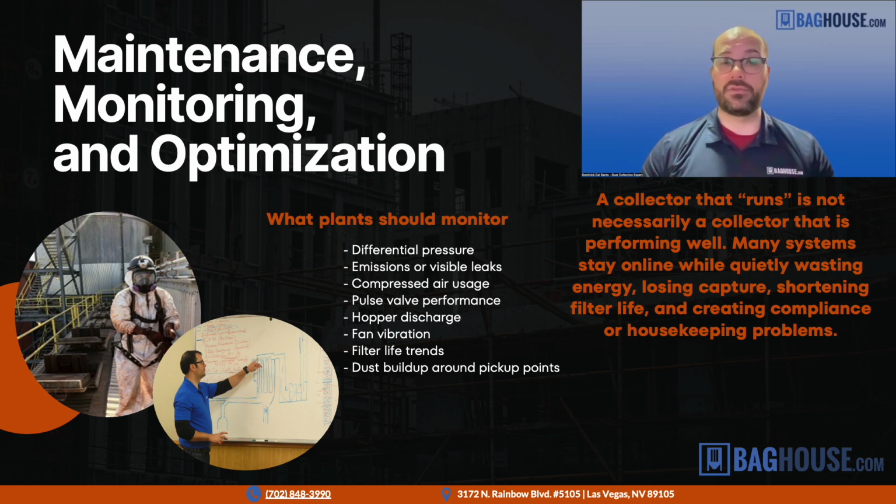Simply upgrading the gauge from a basic magnehelic gauge, which is just a mechanical gauge you look at, to one that has a 4 to 20 output will allow all of those readings, especially those far-flung bin vents on the top of the silos that take 20 minutes to get to and up a 150-foot ladder, to be sent down to the control room via 4 to 20 output. For the extra $50, $80 it costs, it was an incredibly wise investment. So making sure those are monitored at all times. And it's also easy to access, and reduces a lot of unnecessary labor.